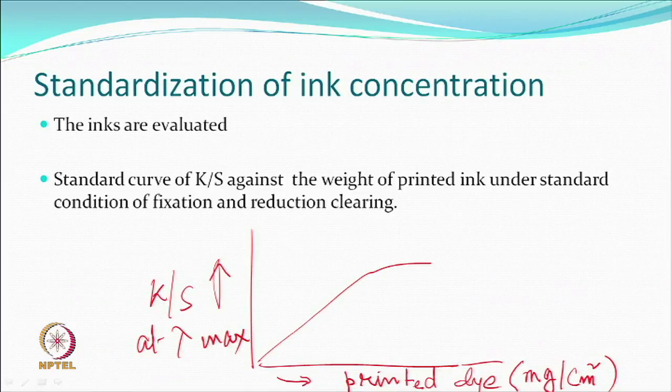So, one is that I have made the process, but when you say you are standardizing, at the end of the whole thing, you measure the K/S value of the printed area under the condition of fixation and reduction. So, let us say you have kept it at 180 degrees in high pressure, high temperature steam, and you see how much the color has gone down. If the same color goes down too much, obviously it will appear lighter.